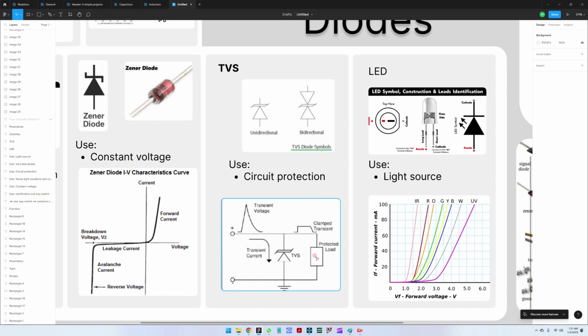This is very important, for example, for automotive or aerospace designs, where you have to somehow protect in case something happens and you have an over voltage. Maybe another equipment inside the car has a malfunction, and it's sending on the supply line, on the battery line, a very high voltage spike. This then has to be clamped somehow, limited, so that it doesn't destroy the whole car here.